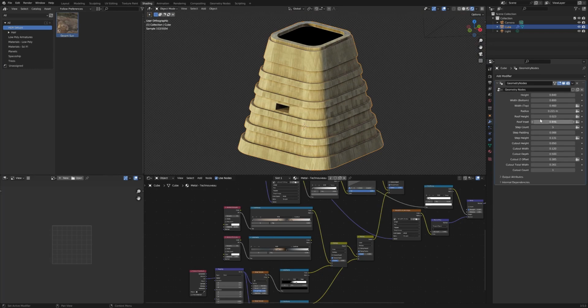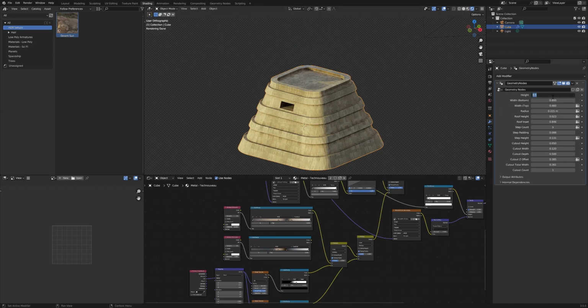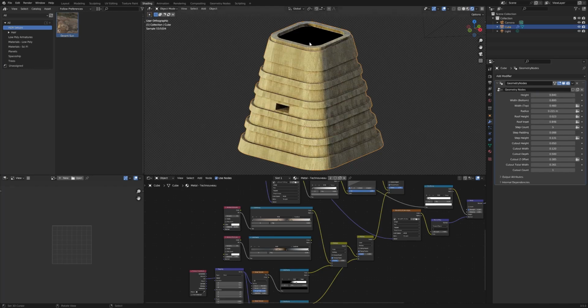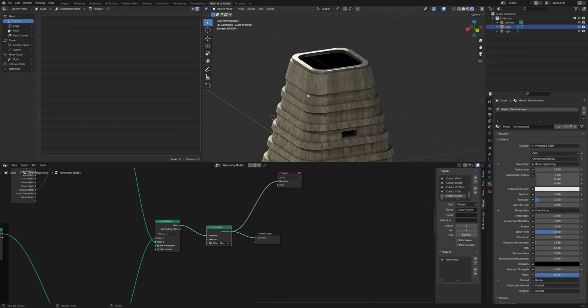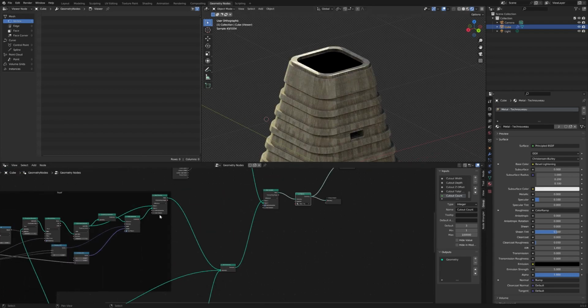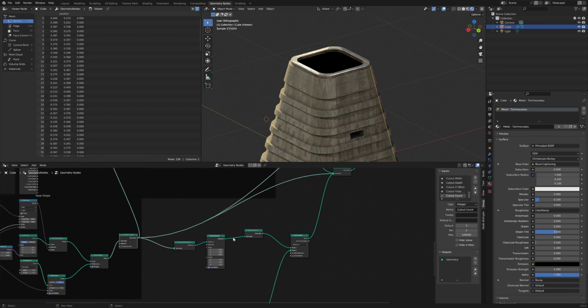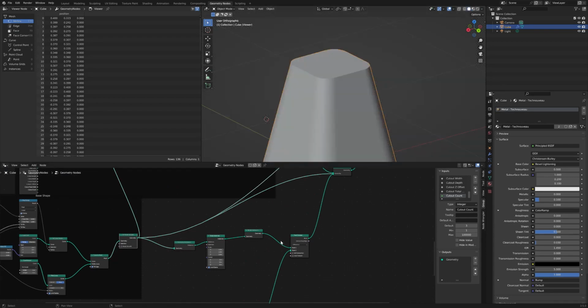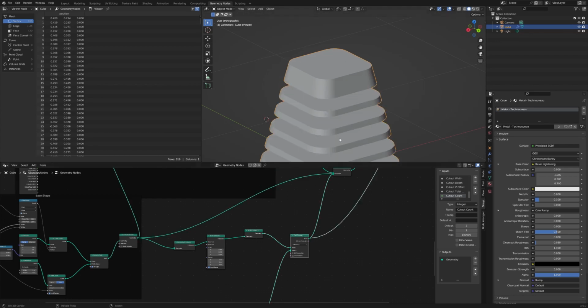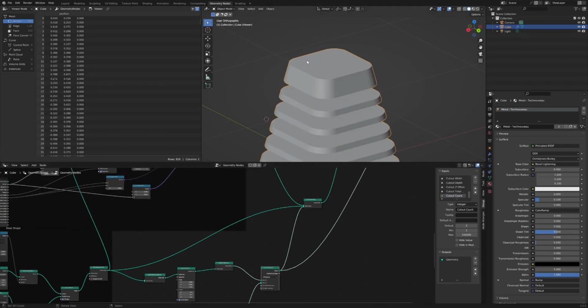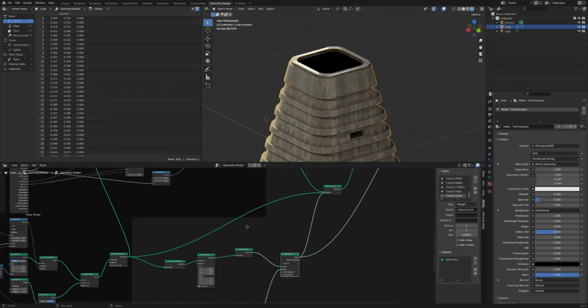So we can go in here and change the height, for example, make it a little bit shorter, 0.5. Although I did notice, if I change that back, we're getting this weird black artifact on the top. The reason for that is to do with our booleans. We have two overlapping booleans. We have the base shape here, if I come out of that, and then we also have the result of the booleans. When you combine them, because their geometry here is exactly overlapping, sometimes you get these weird artifacts, in this case just a straight black.